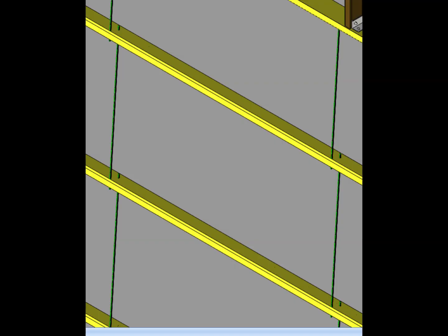Now look at the green vertical sag rod. It is relatively small compared with the main framing members, but its position is intentional. It is not simply placed randomly inside the wall frame. Its location is coordinated with the side wall framing system. You can also notice the small connection or fixing components around the sag rod at the horizontal members. These details become much easier to understand when the model is viewed at a closer scale.